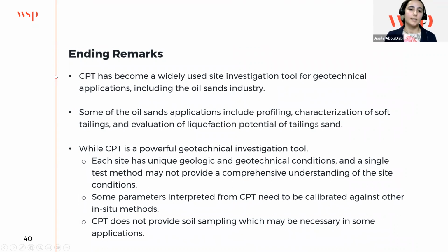So the engineering remarks here: CPT has become a widely used site investigation tool for geotechnical applications, including in the oil sands industry. Some of the oil sands applications include profiling and characterization of soft tailings, and evaluation of the liquefaction potential of the tailings sand. While CPT is a powerful geotechnical investigation tool, each site is unique. It has its unique geological and geotechnical conditions.